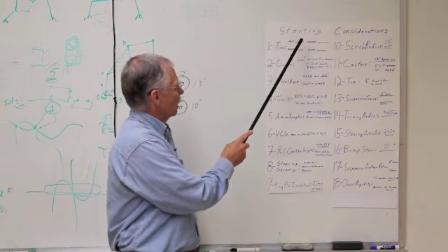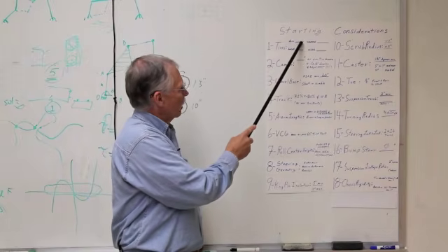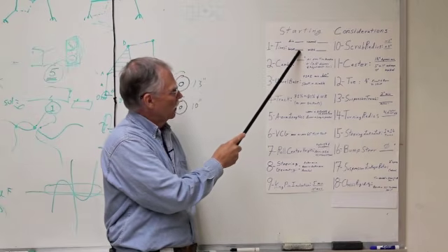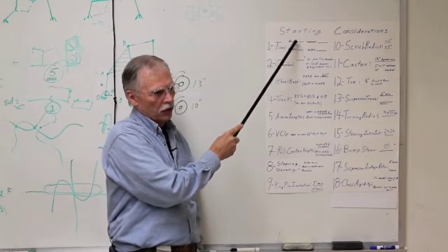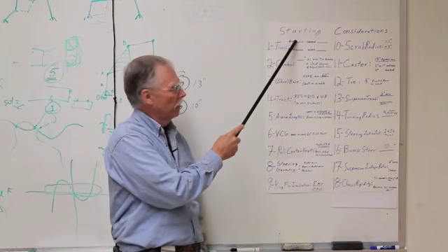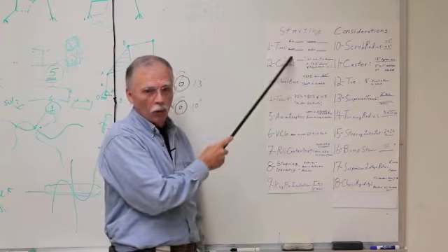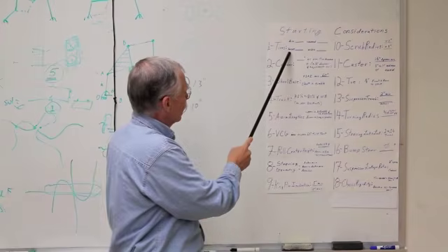So tires, figure out the diameter. Then figure out from that diameter which tire you're going to use, which will give you the height. It's important to know the height because you need to know the radius from the pivot of the wheel to the ground, that radius length, because that's going to determine some more geometry down the road.